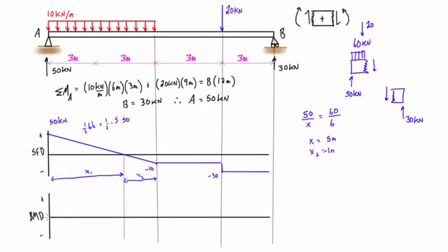We know that this beam has a bending moment of 0 at the ends, because it's not a rigid connection. These pins can't build up any internal bending moment. So the beam starts at 0 and ends at 0. In this first section, from 0 to x equals 5, the increase in magnitude is this area, which is 125. These are in units of kilonewton meters, and up here these were units of kilonewtons. Cool.